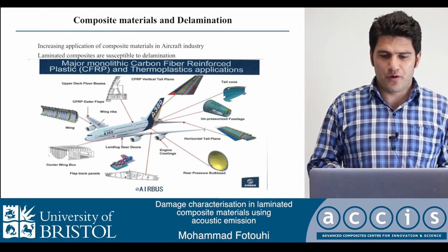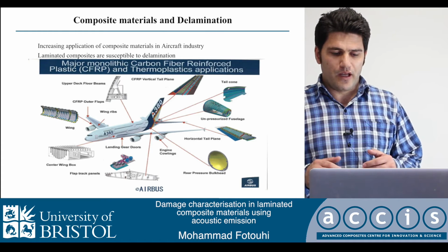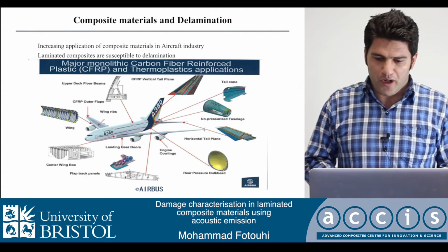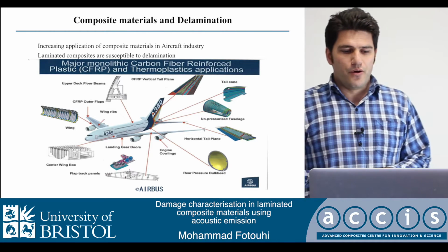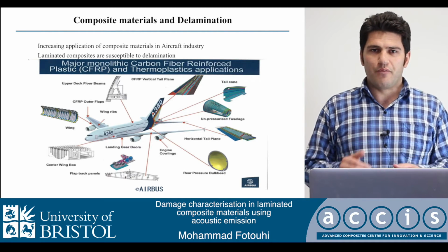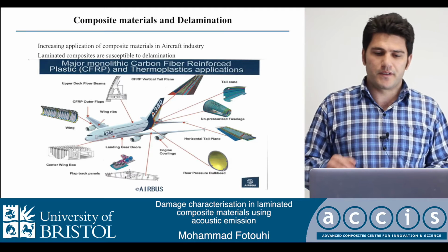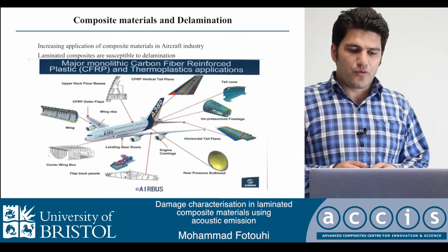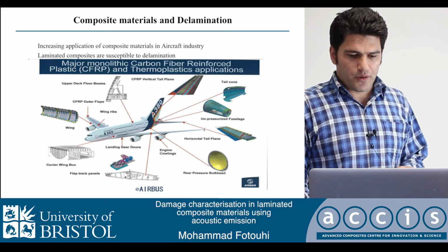As many of you know, composite materials are very useful, and most parts of the structure of aircraft nowadays use this kind of material. They are light and they have many benefits. Besides, they have some problems. Most of them are related to susceptibility to delamination. They are very sensitive to damage mechanisms because of their complex structures, and we want to detect and determine this kind of damage using a novel technique which is called acoustic emission.